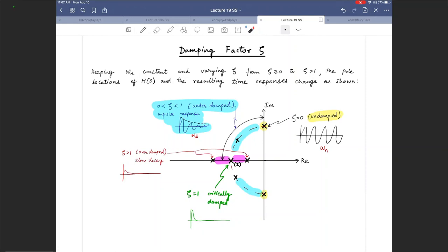That is called the overdamped case, and that leads to a slow decay. So the amplitude, the strength of the response, is not as high as the critically damped case. No oscillations because we have killed them with increasing damping, but there's a slow decay that results from this.